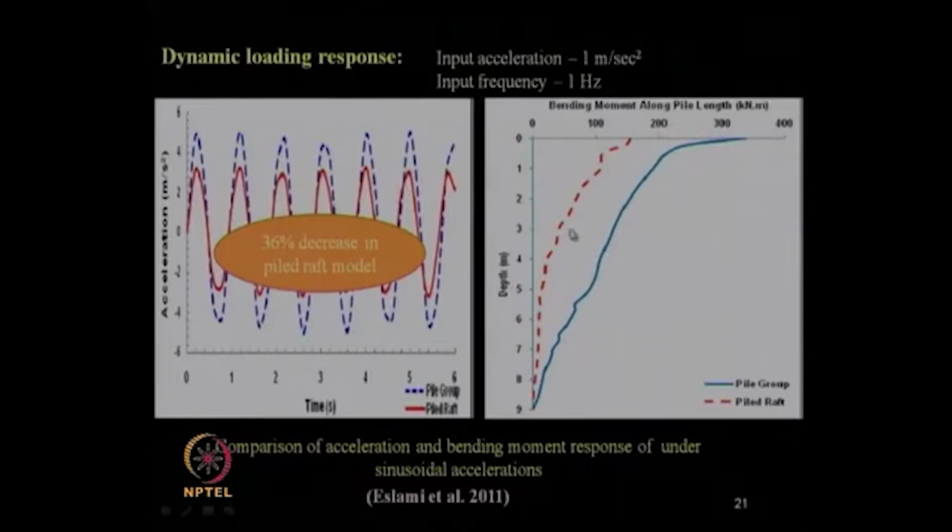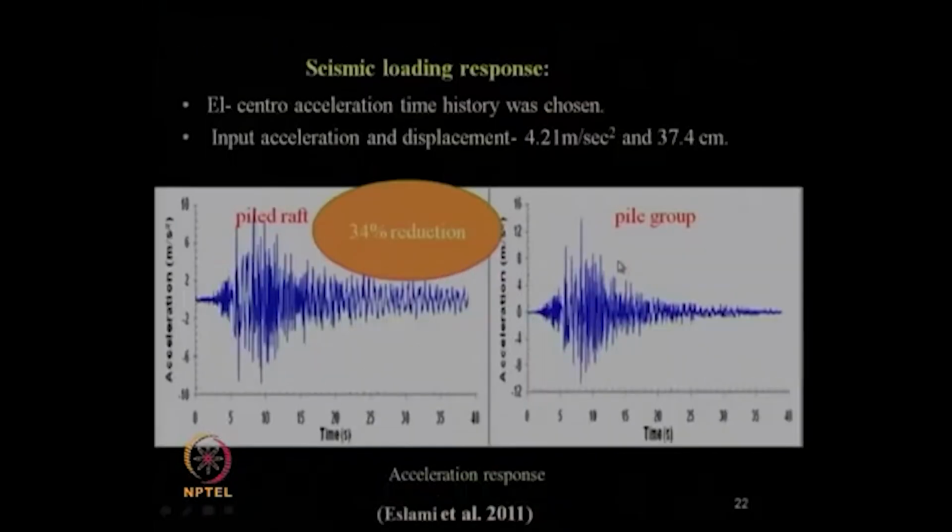Why does it occur? Because here the load sharing between the raft and pile is going to take place in the dynamic case as well. And these researchers mentioned a 54% decrease in the bending moment of the pile raft model using this CPRF technology under dynamic loading condition. Also, Eslami et al. 2011, they used the seismic loading condition also.